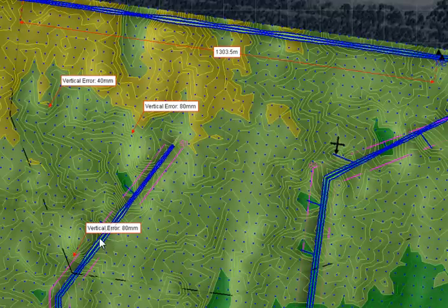So this is the proposed topography map, and these contour intervals are around 30 millimeters, around 1 inch. So where these contours change, the closest together, that's where we'll end up with the largest error in our design because of that horizontal error. So looking at these contours, the error at these locations could be around 80 millimeters at that location, 80 millimeters here, and about 40 millimeters at this location. The rest of it's going to be less than that.